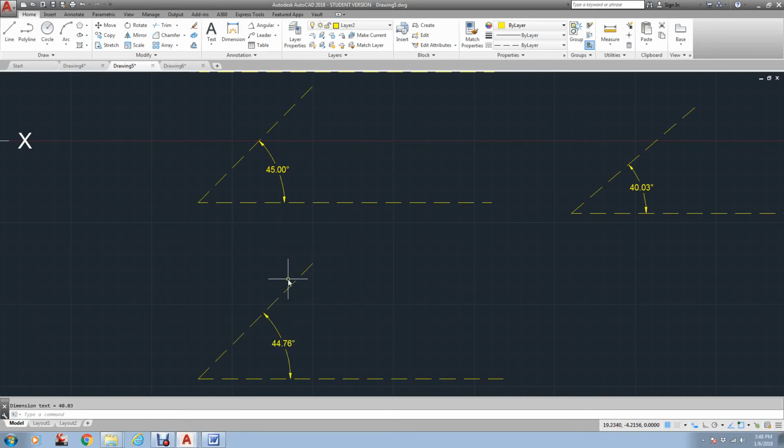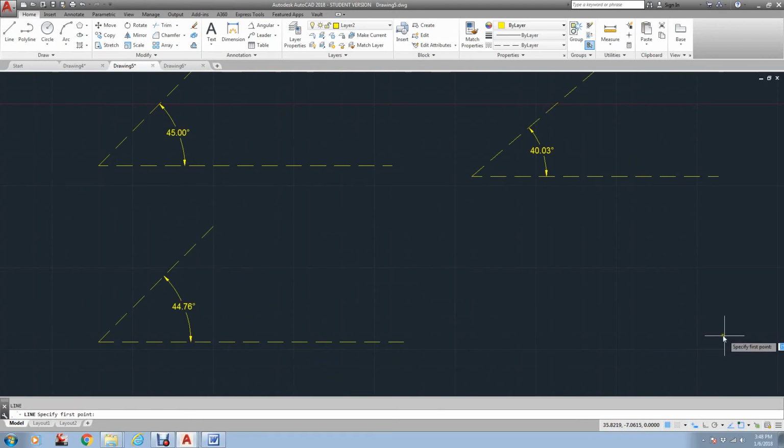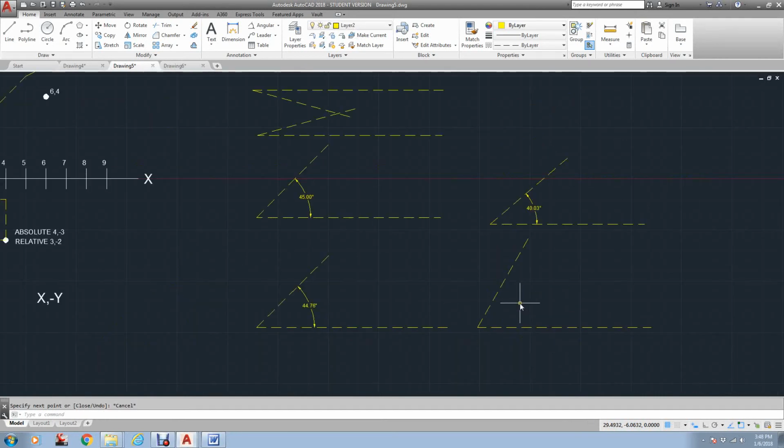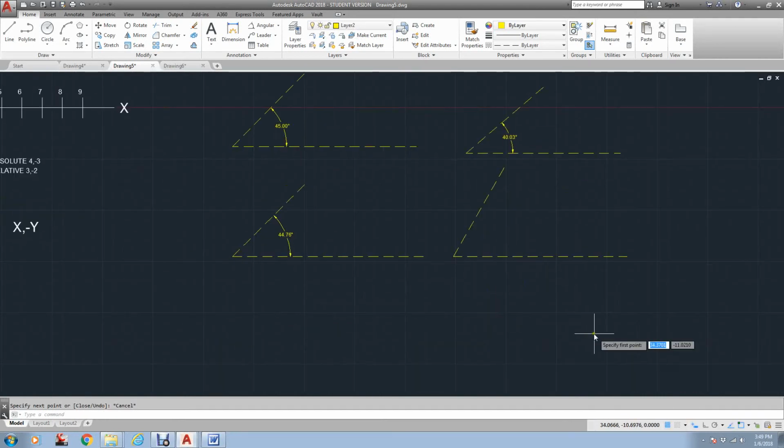So to do it exactly, once you've drawn your line, when you're coming back, you have to hit 5, shift, and less than, and then say type in 60. Okay, now again, I'm going to do that again down here. I'm going to go line to right about there, and I'm going to go 5. Oops, I'm sorry.